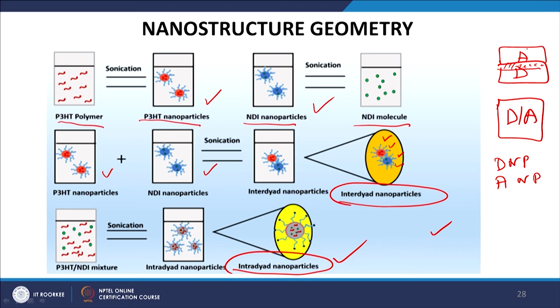To overcome that, we mix them together to make a phase-separated bicontinuous percolated network. Similarly, if we electrostatically attach them together, the distance between the donor and the acceptor is higher than if we mix them together, where the probability of seeing the acceptor by the donor is much higher than in the interdyad case. So the consequence is that not only the morphology by the self assembly, but the charge transport dynamics will be completely different in here than here.